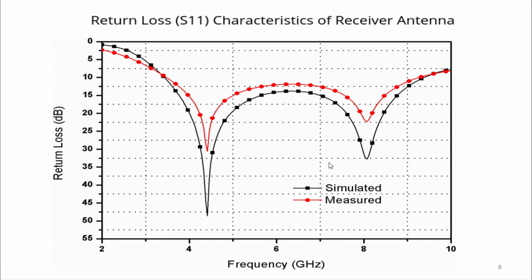So here we have an example of ultra wideband antennas. If we take this antenna, we have return loss in decibels and frequency in gigahertz. If we go toward minus 10 decibels here, we can find that the return loss is inferior to minus 10 decibels between this point, I think 3.2 gigahertz.